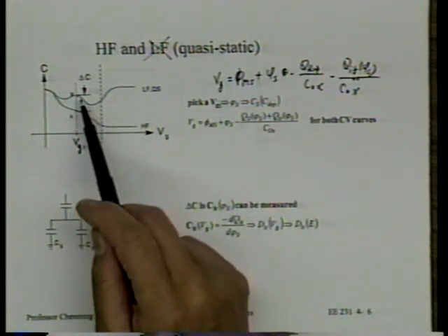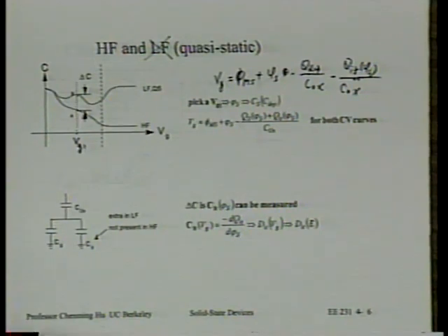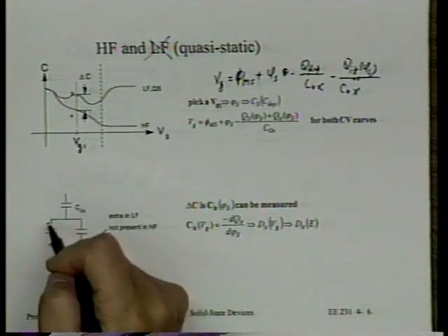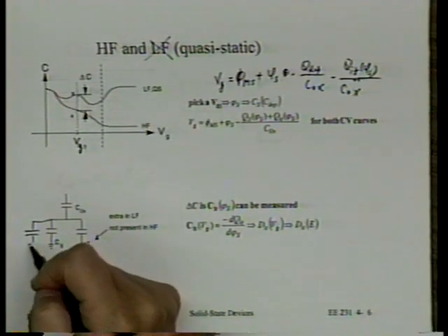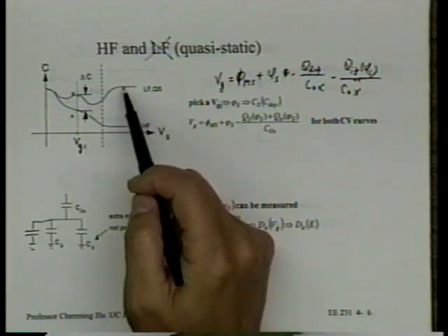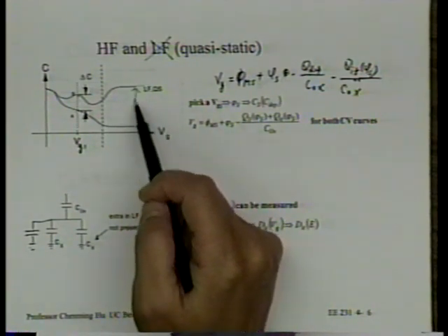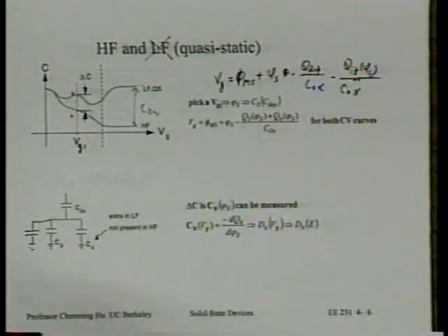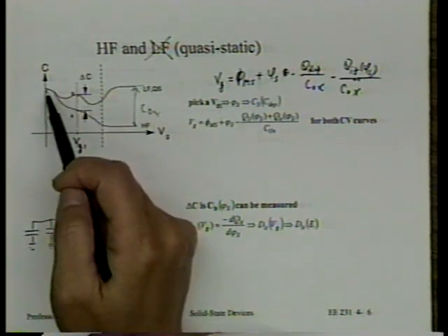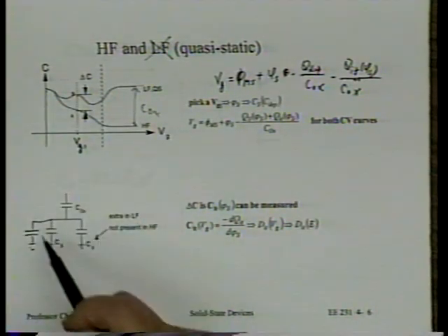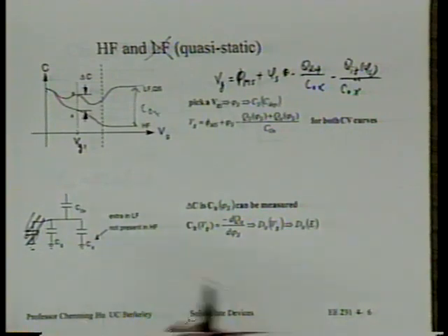I'll answer the question first. The question: where's the inversion capacitance? In both cases, I have crossed out the inversion capacitance together with the accumulation capacitance. Again, there's no information we can get there. The difference is just Cox in the inversion layer. There's no information we can get here. They just coincide, so those totally go out. It's only applicable in the depletion region.